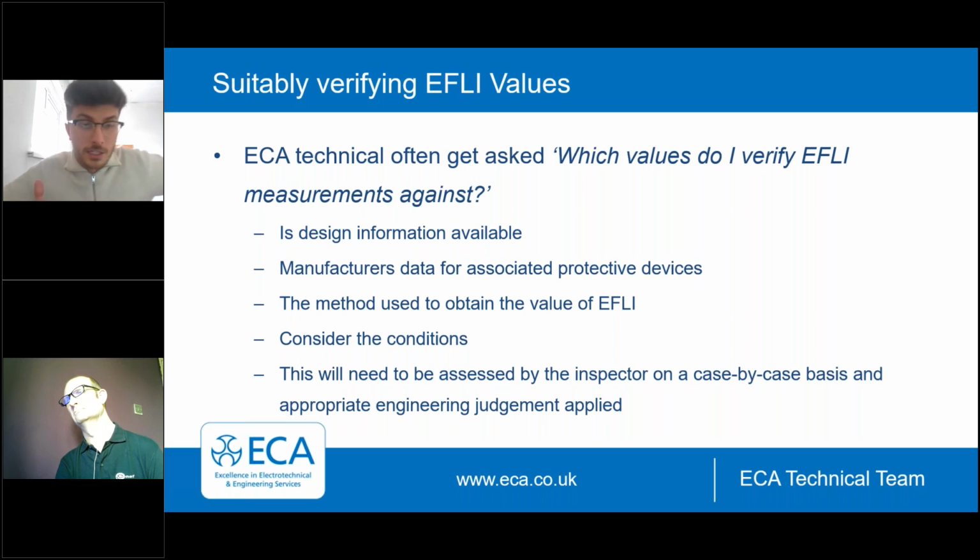In terms of the maximum earth loop impedance value permitted that you record on the schedule of circuit details, generally it's the value within BS 7671, although there are some notes under the table that say you can use other values. You just need to detail that you've used other values and, where relevant, provide the relevant documentation.